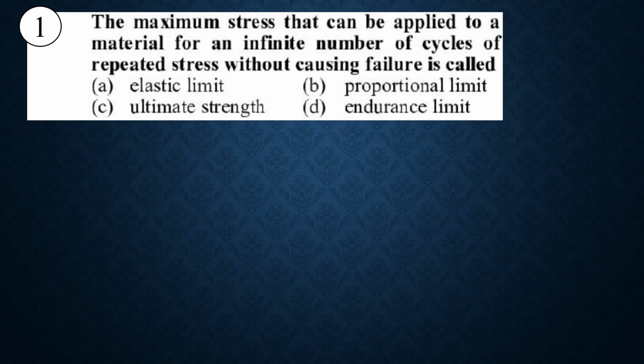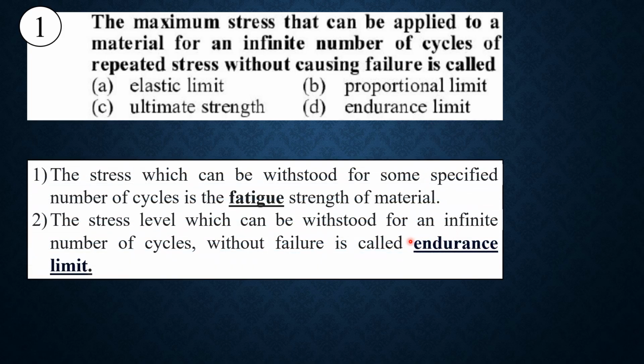First question: the maximum stress that can be applied to a material for an infinite number of cycles of repeated stress without causing failure is called endurance limit. Another similar term is fatigue, but fatigue is with a specified number of cycles and endurance limit is with an infinite number of cycles. So option D is correct here, but the other three terms in options A, B, C are also important.